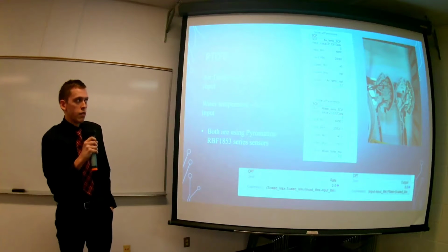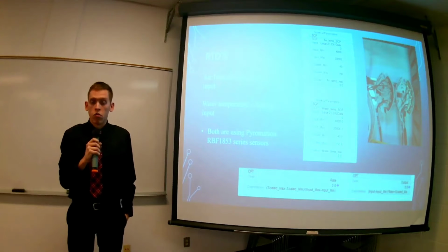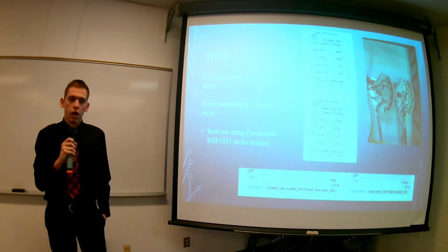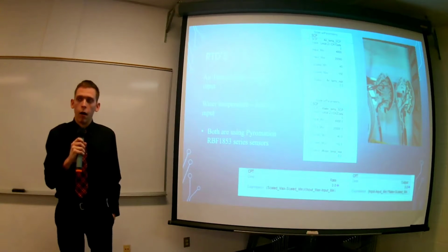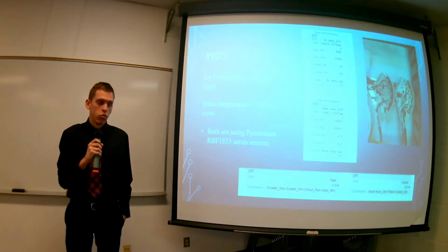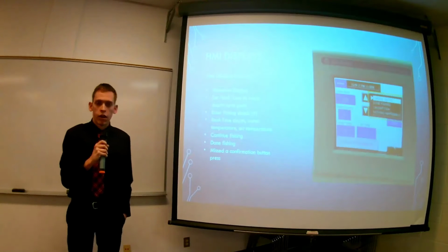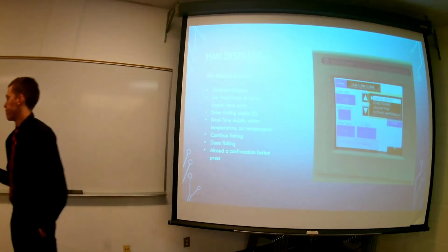So all it's doing is taking that input value, which is somewhere between 4,000 and 20,000, so your 4 to 20 milliamp, and then converting that into a degrees value in Fahrenheit that we can understand and then display to the user. So with that, I will turn it over to David, and he'll go over some of the HMI and some of the programming as well.